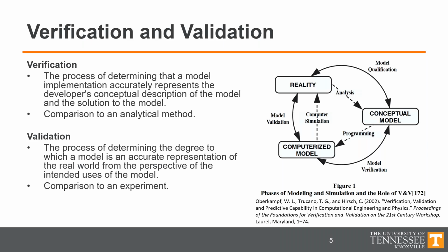Now, for engineers in the United States, probably the most important and natural point of comparison for IDEA StatiCa is to the specification provisions in the AISC Specification for structural steel buildings. This comparison doesn't exactly fit into either of the lengthier definitions that I have on the screen here, but recognizing that the AISC specification doesn't always reflect reality, and following the IDEA StatiCa definition as well, we're really going to describe these comparisons as verification more than validation.